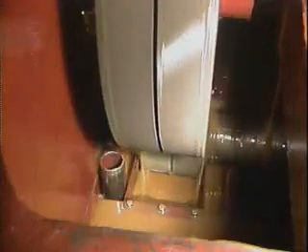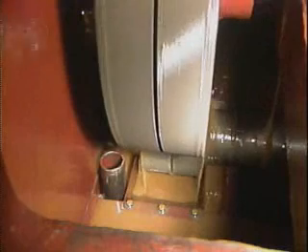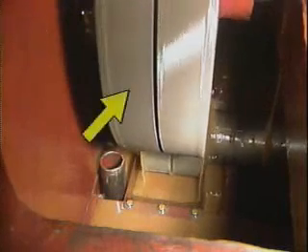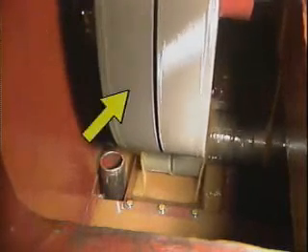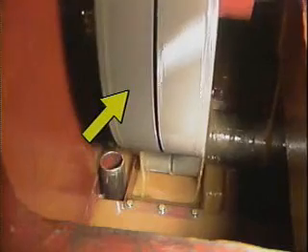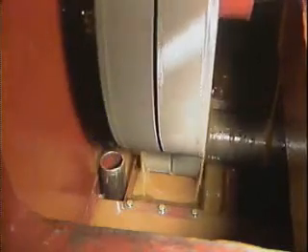Solid lubricants, such as the material whose trade name is Teflon, are also used as chemical coatings that prevent metal-to-metal contact by providing a solid covering for a metal surface. Chemical coatings are generally used in combination with another kind of lubricant. For example, if an oil film breaks down and allows two surfaces to come in contact, the chemical coatings provide backup lubrication.